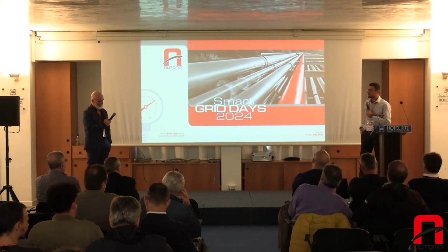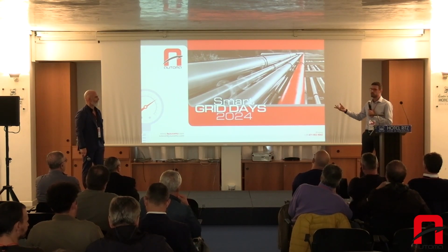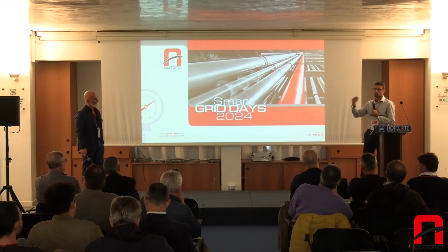To answer your first question, yes, if I act on a structure which, due to corrosion, I've lost millimeters or microns of steel, that doesn't mean that if I install the system, I am going to recover anything structurally. What I do with cathodic protection is just to block the corrosion.